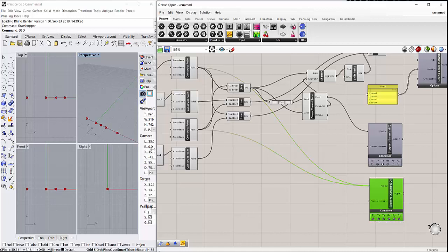So what I'm trying to do is I'm trying to make this beam fix at these points, and this support is not going to move in any direction or is not going to rotate at any direction. Same goes for this. So only this part will act as a beam which will bend on the Z direction.